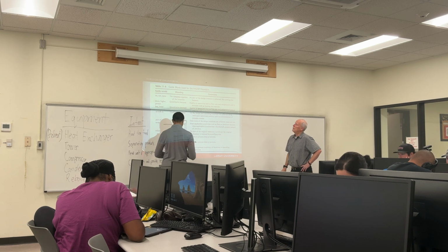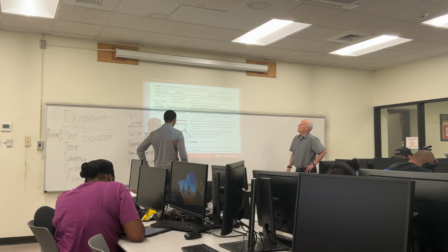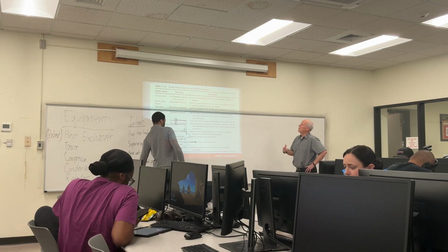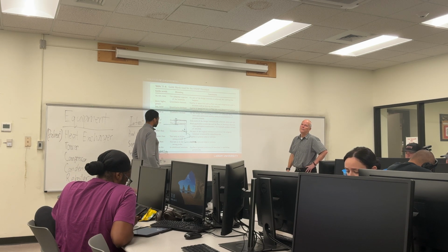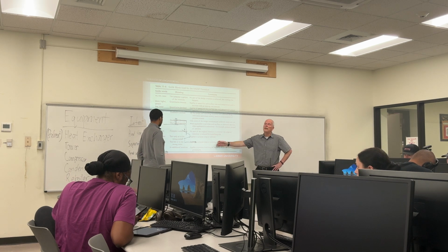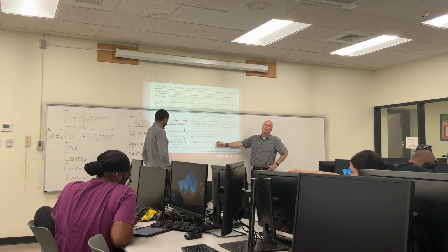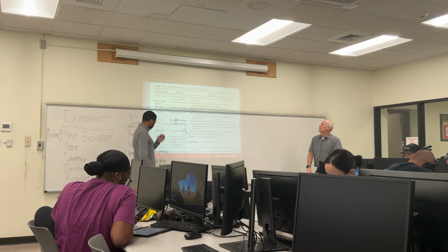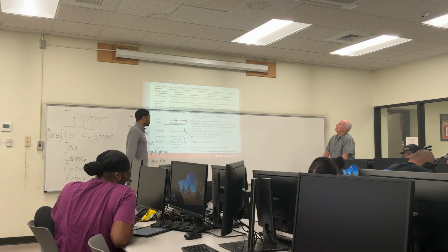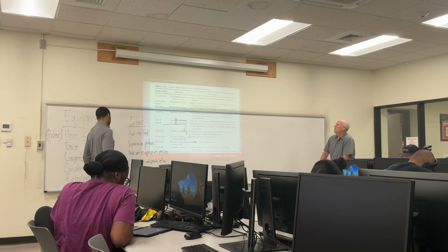Okay, so the idea is that you adjust the speed of the compressor to achieve a suction pressure. That's the way. You can't control it by adjusting a valve on that like you can on the car. Compressors just don't work like this. Okay? So the design intent was to what? Feed the unit at the appropriate pressure?